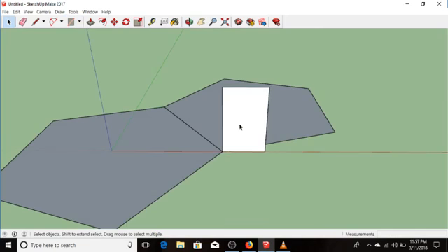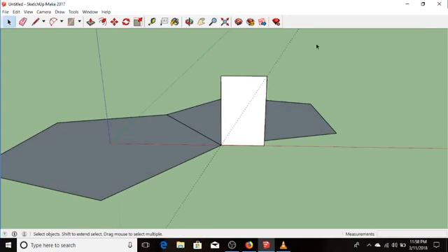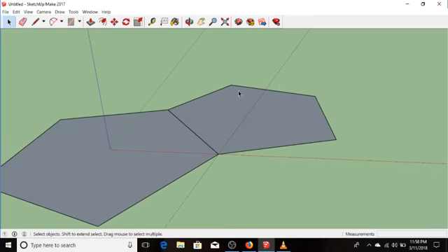We need this angle here. One of the functions of the measuring tool, besides measuring, see it's 0.76 meters from there to there. It's 1.23 meters from there to there. Well, another function of this is to draw in guidelines. So if I click here and click there, it draws in a guideline on that angle. So that's my guideline. I'll get rid of this. That's my guideline.